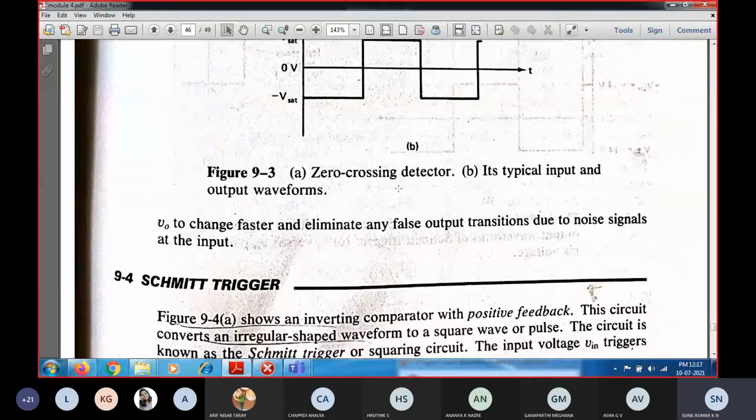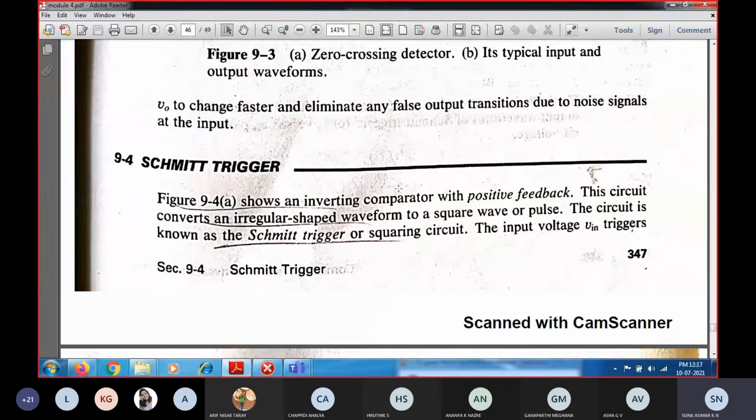So there is a correlation between the open loop amplifier as well as positive feedback. Whenever the op amp is acting as an open loop or in positive feedback, both will have the output getting saturated. So even if you employ the open loop amplifier configuration or the positive feedback amplifier configuration, the output of the op amp will be in positive saturation or negative saturation only.